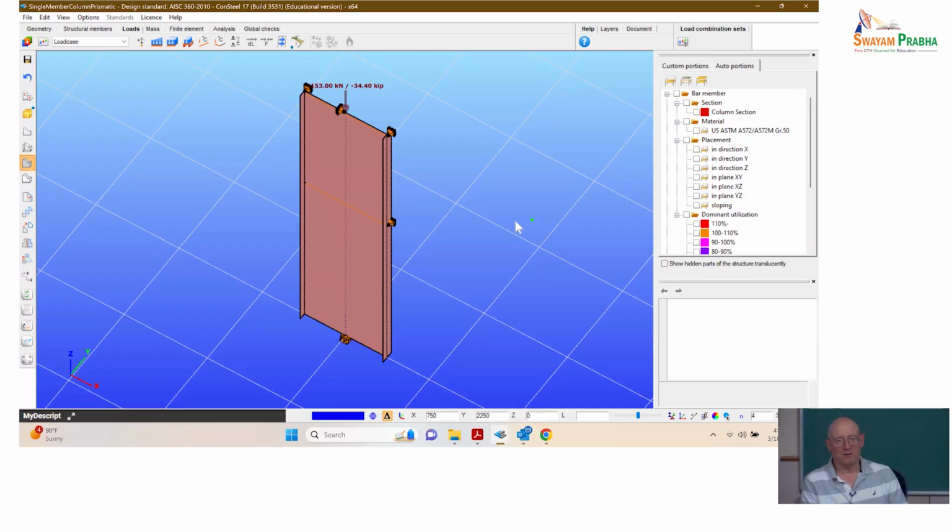You can go a little bit thinner than that before you hit section F13 of the AISC specification, which puts a limit on how thin you can go before the specification doesn't allow it. You can go to about 220, 230 or so with grade 50 steel, I believe, if I'm going from memory here. We can look at that equation later.